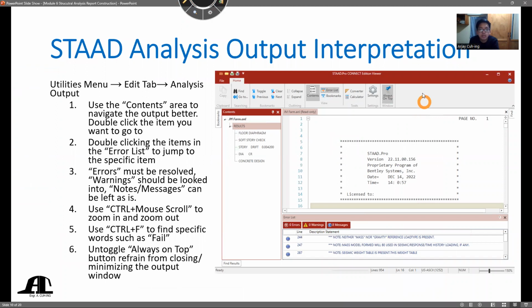Okay. So next up class, that is how we open it. Secondly class, supposedly we can interpret. We should learn to interpret. Kumbaga, imagine yourself as the building official in CBAW. Tapos you are to check class their submission in terms of the structural analysis. Did they do dead loads or live loads only? Did they consider earthquake loads? Is wind load included? Tama ba yung mga loadings nila? Nag-loading combination ba sila or simpleng dead load plus live load lang?